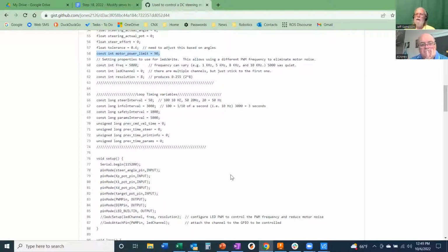So you crank your pot back and forth, and it'll say it's right here in the center, and you set it over to here. Say your hard stops are over here; you don't want to get anywhere near. So set your limit out about here. As you crank your pot, the motor whirs and then just stops when it gets there. You back the pot off, and once you move those lines of code, it should back off and control. So it'll control within these two limits that you're calling your safety limit, and your hard stops are way out here. Move it way in when you're first playing around and make sure you're nowhere near the hard stops as this is working, because it will surprise you very quickly, and it's better to not slam into stuff.